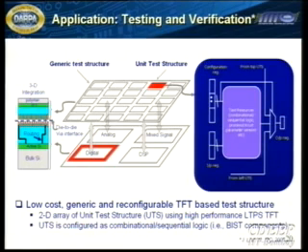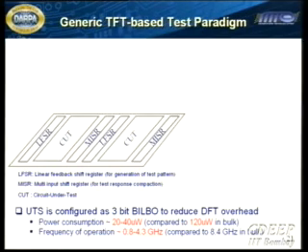What I'm really not talking about is what these different test structures are like. If you're interested, I can refer you to one of our papers. But the interesting thing is that it would give me something that I can use to test my underlying CMOS circuits. And I can offload some of my test cost from the external tester into this circuitry. So a very simple-minded analysis would do. Those of you who are familiar with linear feedback shift registers and so on, people have been using them in today's design a lot. So potentially what one can do is have the CUT, which is a circuit under test, and along with that, on the two sides, you have these LFSRs and the MISRs. MISRs are also some sort of a compactor.